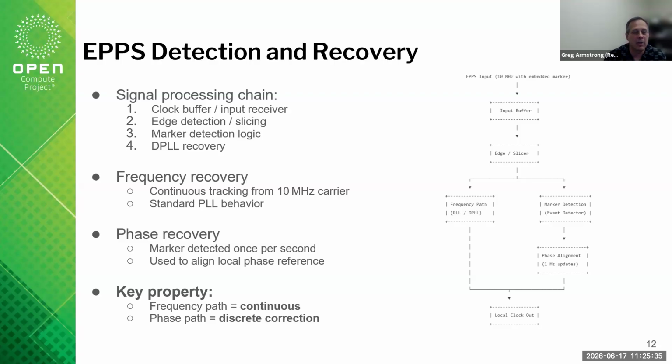And then you're going to maybe look at it saying, well, is it looking at the high edges? Is it looking at the low edges? Right? There's probably some sort of phase detector that's done already, especially if this is going into a traditional phase lock loop, or PLL, or even a digital phase lock loop. It needs to basically do its own phase relationship, but it's looking at every edge of that clock. So it's looking at the 10 megahertz clock and looking at the edges.